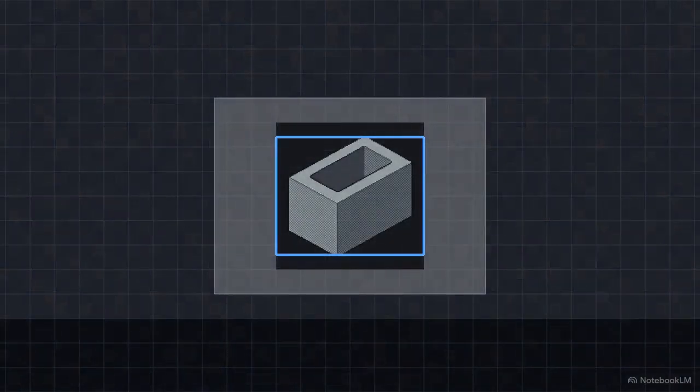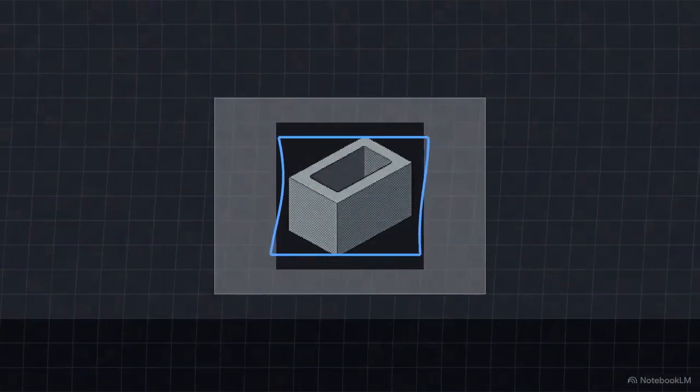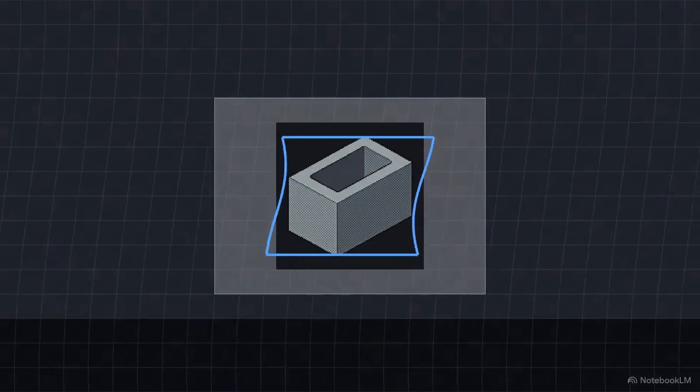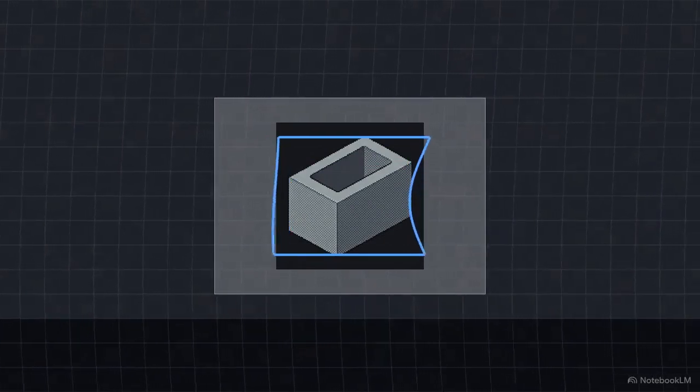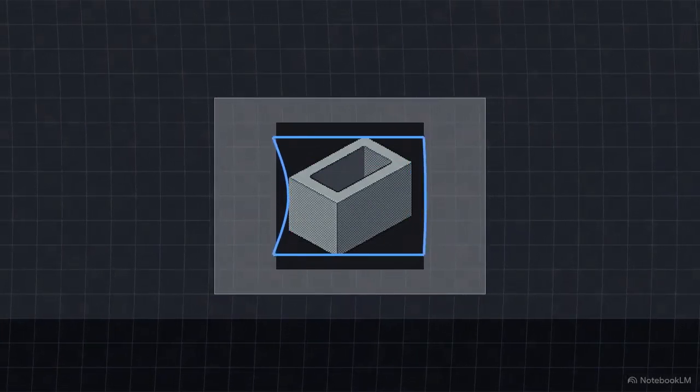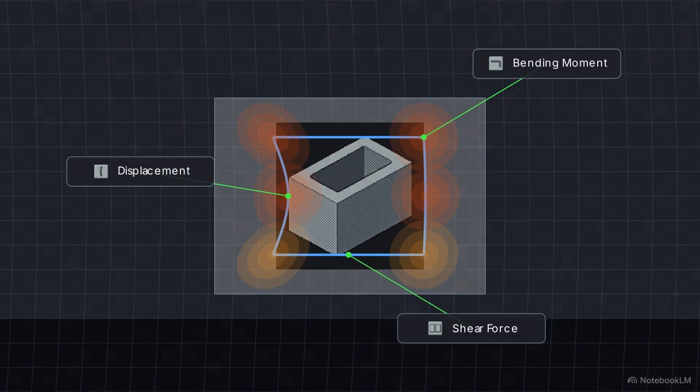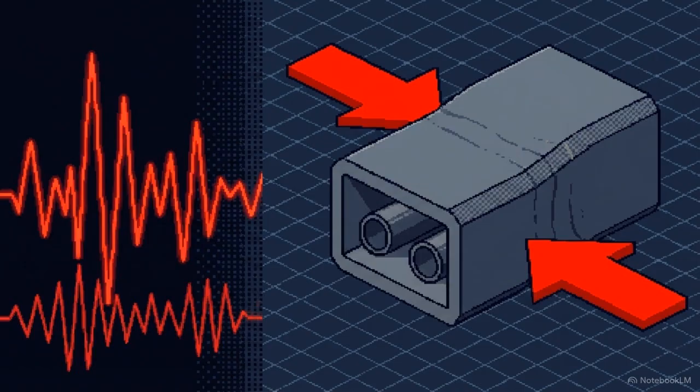In this combined cross-section, SHAKE's input wave is injected at the model's absolute bottom. As the wave forces upward, the software calculates the soil-structure interaction. FEM outputs highly specific stress measurements: the exact degree of concrete bending, joint stretching, and surrounding physical soil pressure. This 2D FEM phase proves exactly how the structure will physically deform under stress. It successfully turns abstract wave data into measurable forces.